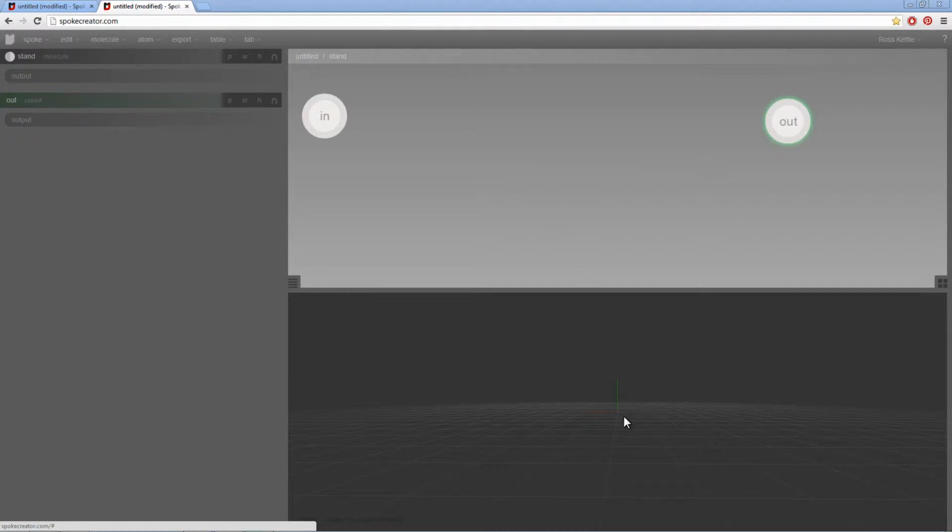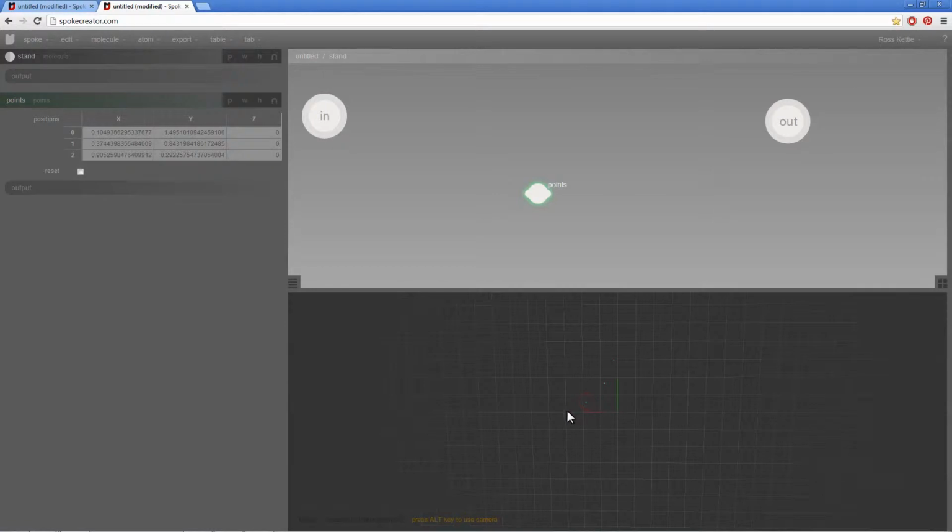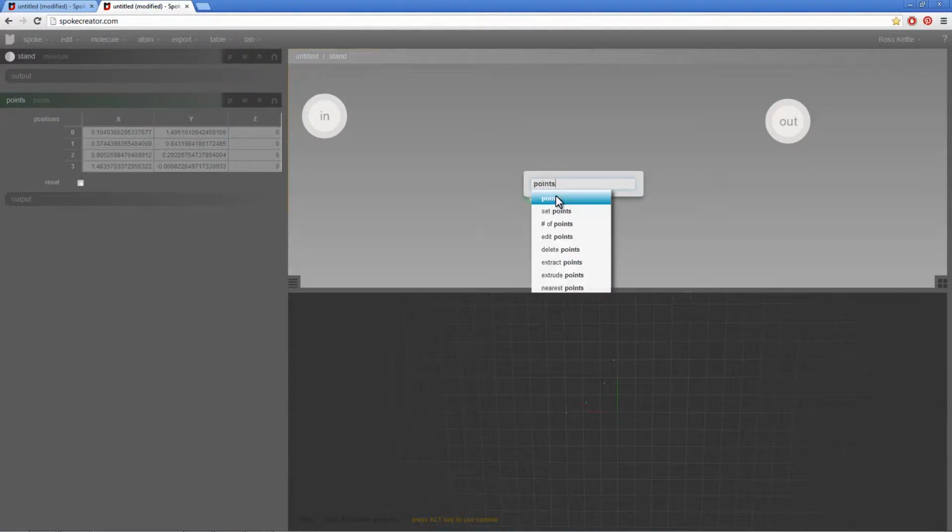So I'm going to switch to a front view ground plane, so that when I create a points atom, I can just draw directly on that, and I'm going to draw a profile for a curve and connect those points together with a points to curve.